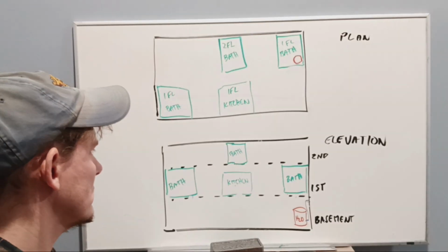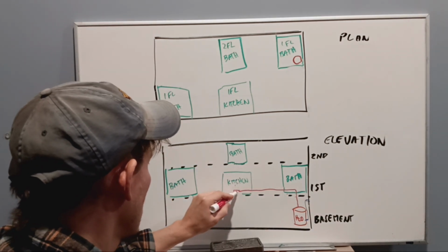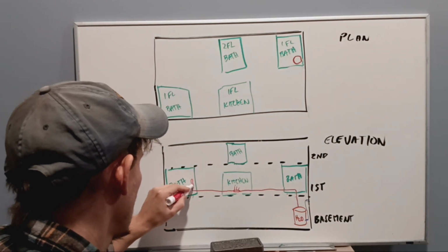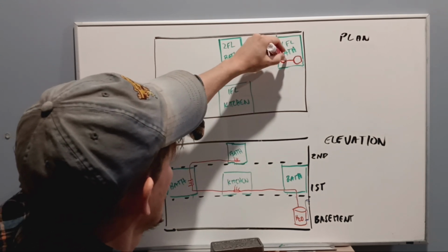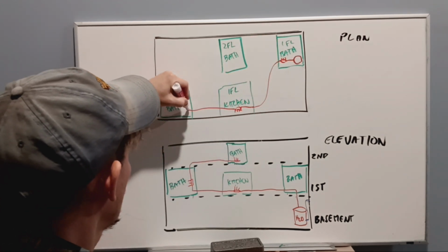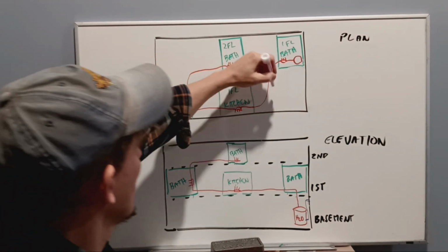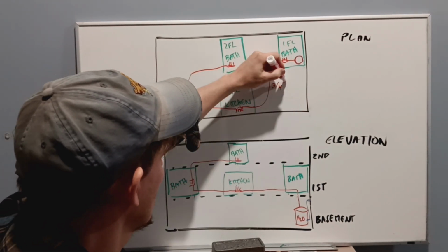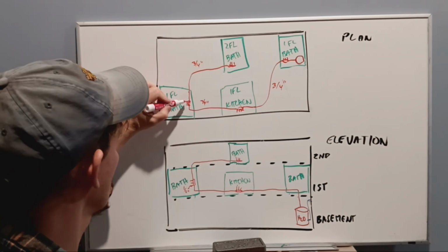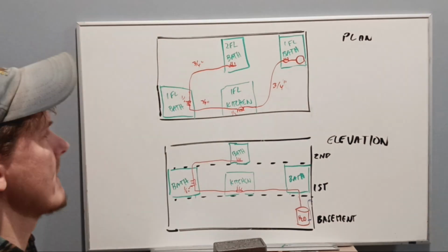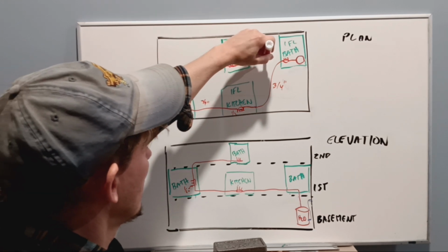In a potable hot water circulation system, the hot water comes from the hot water tank and it runs to each user in series. In my system, this is 3/4-inch PEX, which has about twice the area of 1/2-inch PEX, so that it can reasonably support 2 users concurrently. At each location, a manifold branches off 1/2-inch PEX to separately support a sink, tub, shower, or other hot water user. After the last user, the hot water line runs back to the hot water tank.